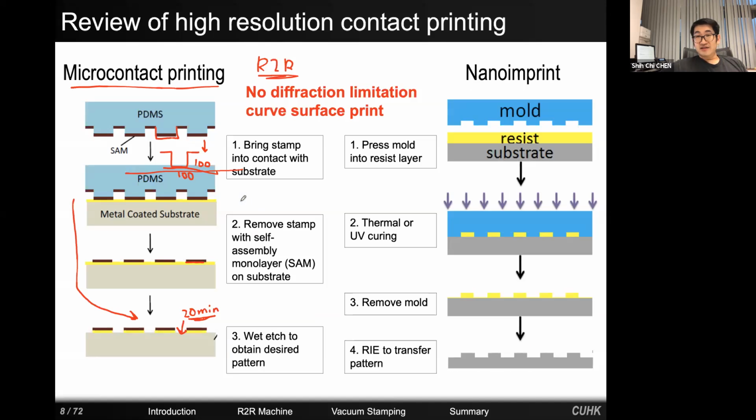In fact, nano imprint is easier to implement because the mold is a hard mold. And it's printing on, for example, plastics using thermal forming. So overpressing is still going to result in reasonable patterns. Or UV epoxy is applied, and after rolling, you will still have features, unlike microcontact printing.